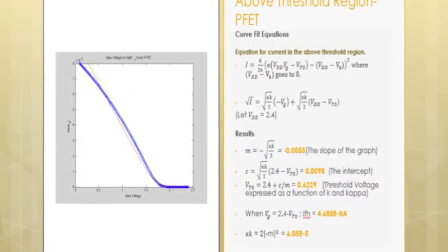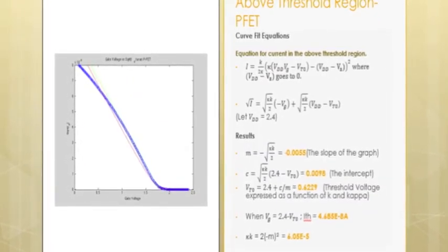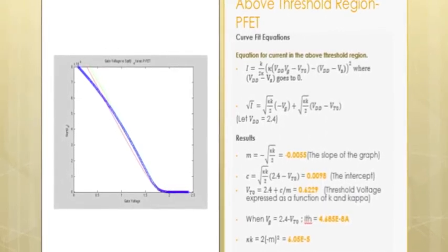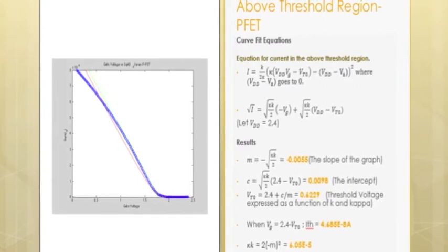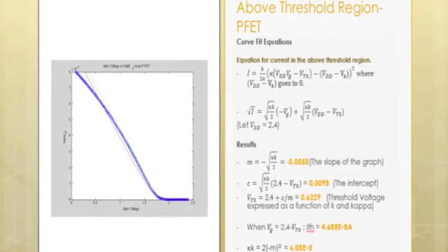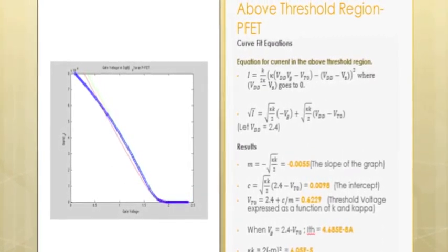Moving on to the PFET gate sweep, for the above threshold region, we use very similar equations and techniques to find the same parameters but for the PFET. As you can see from the simulation and the experimental data, the PFET is a flipped version of the NFET.